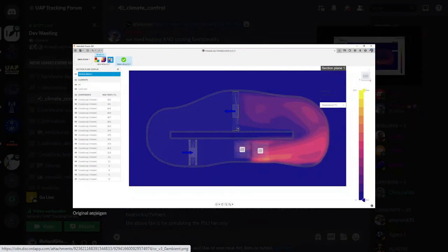Yeah. The top fan you have shown in the loop, is that representative of the PSU fan? Yeah, right. Exactly. The PSU fan going out of the output, that's what, 40 CFM? Yeah. Plus the fan that sits on the Nano, which is about 15 CFM. So if you just add them up, theoretically, you come up to 55, and I've chosen 55 CFM for that rotor here. But we're trying to maintain the loop at that CFM, just so everyone knows.